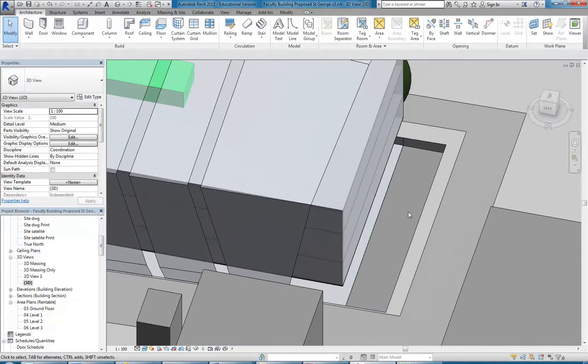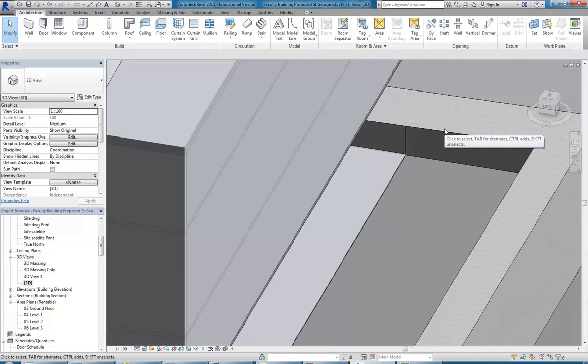And this is another thing you maybe want to think about as you're starting to set out the envelope of your building, where you have a wall that's up against a part of your site that's cut away. Obviously that's going to be a retaining wall, and if it's subterranean, in other words, probably in your car park or your basement, then you need to have tanking. And are you doing tanking with George? Yeah. So that's just a detail that you'll need to consider there.